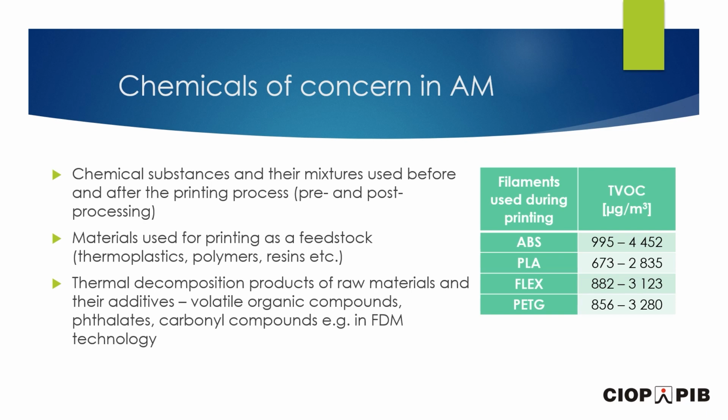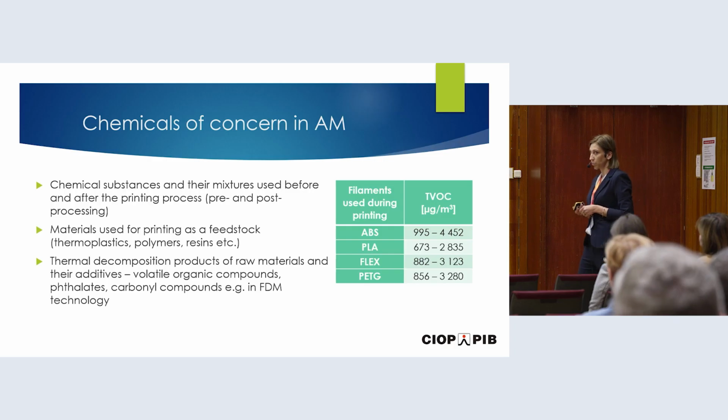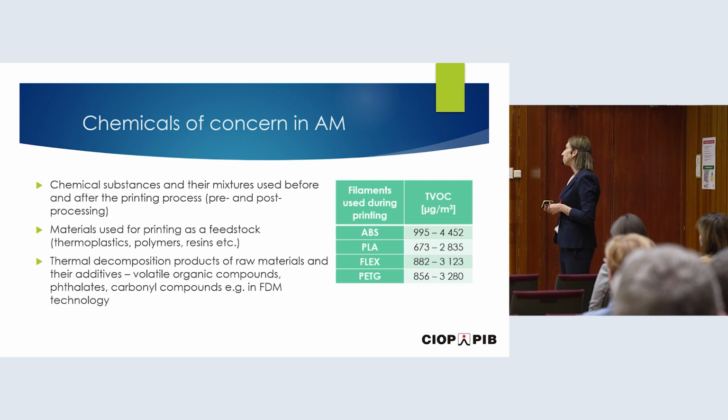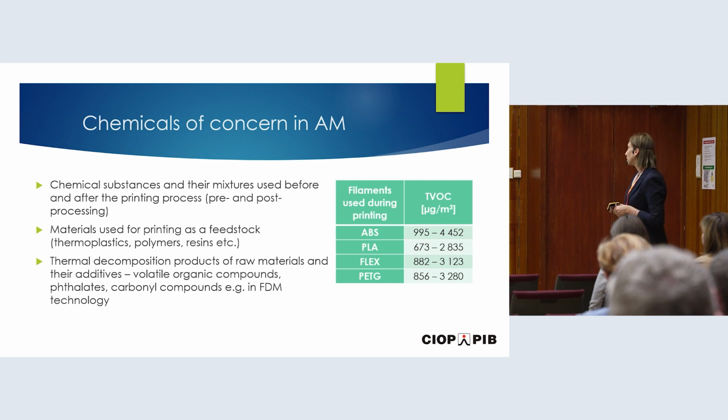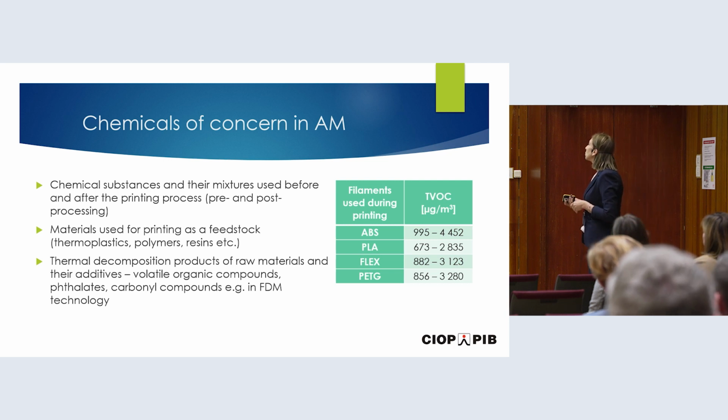And then the emission, so the thermal decomposition products of both raw materials but also the additives that are used to prepare those filaments. For example, if we talk about the FDM technology, the most popular one, fused deposition modeling. We have performed a first test in our institute that covered the analysis of chemical compounds and also particles at the workplaces where different people used the FDM fused deposition technology. We found that depending on the filaments used during printing,